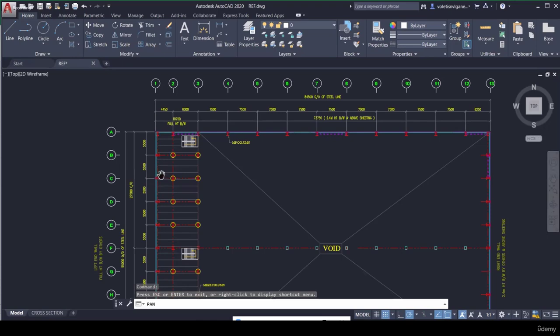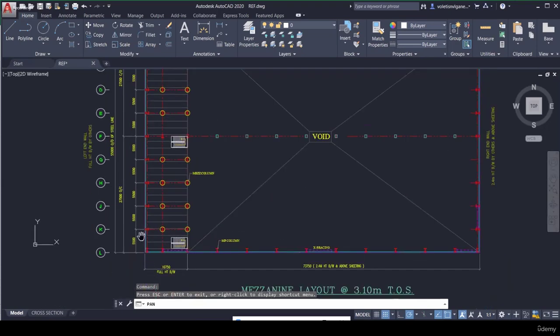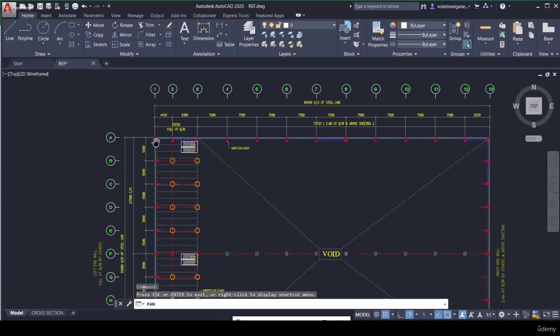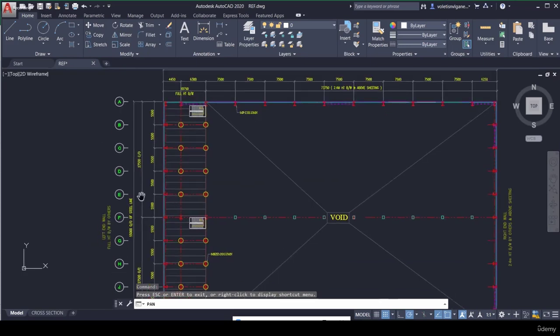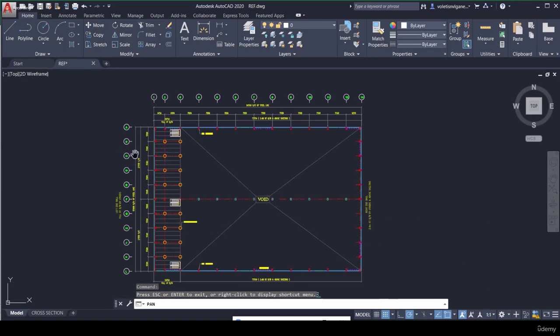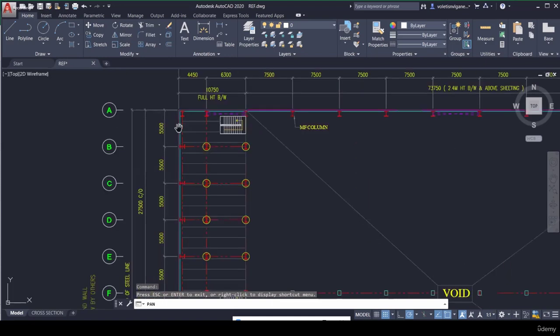So if we provide bracings here, the sections will be lighter. That's why the end frame with bracings can be called a light end frame. Otherwise, it can be called a half bay loaded main end frame. In case there is any future extension, in case any customer wants to extend the building in future, we have to design it for full load width.